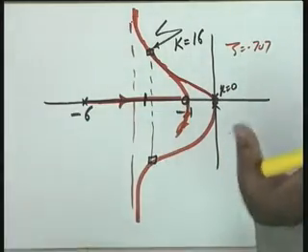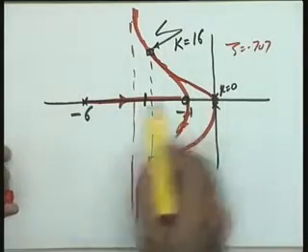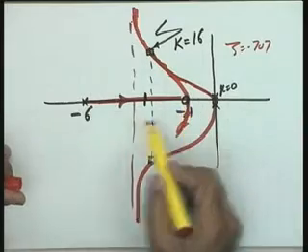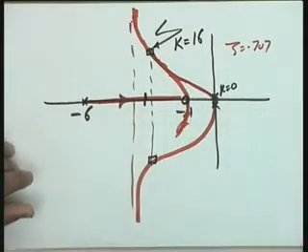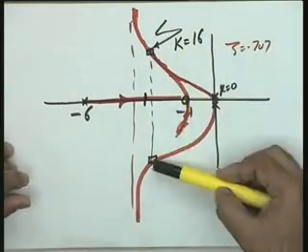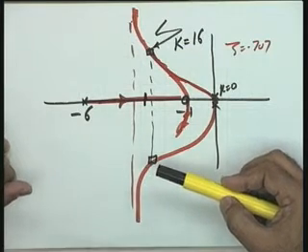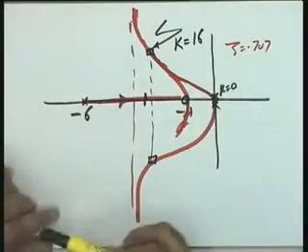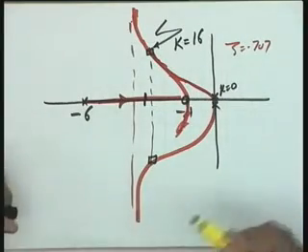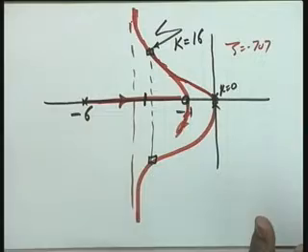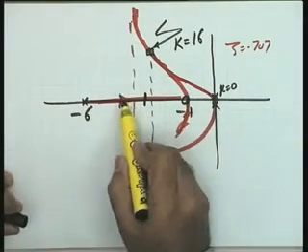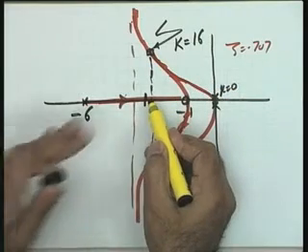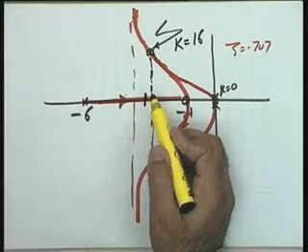So there is no other clue other than this, that this 0 can be adjusted on this particular axis suitably, so that the dominance condition is fairly satisfied, so that these two complex poles are truly representative of the transient response of this system. Okay? Some clue can follow, and that clue is the following. If possible, in this particular case it is not possible, if possible you place your 0 in this side, that is, if I take this as the vertical line, on the left hand side of the vertical line. Can you give me a reason?